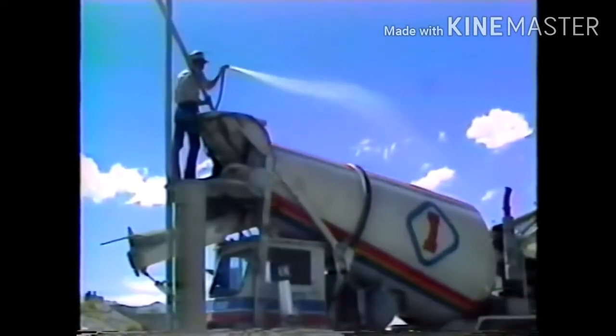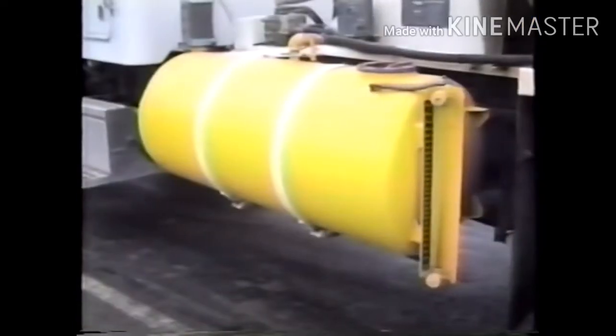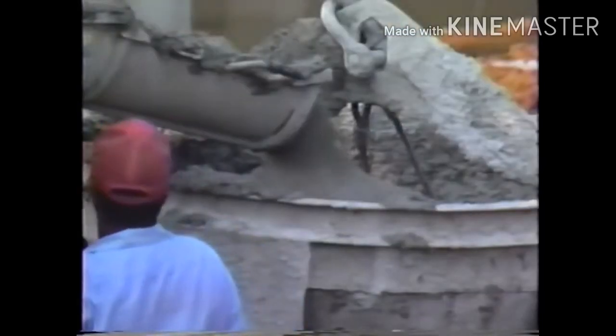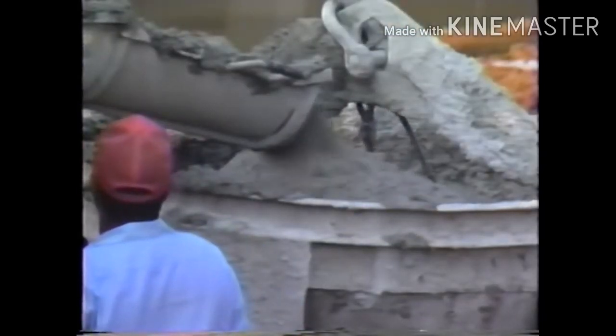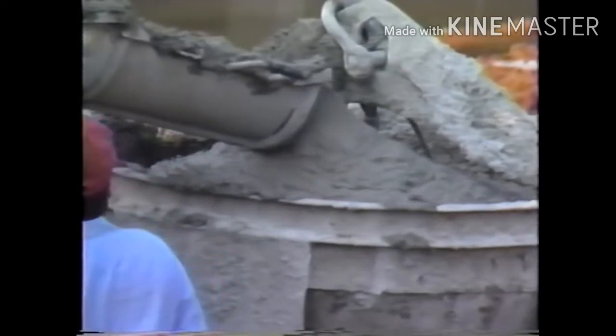For example, if wash water was left in the truck before it was loaded, the mix may be too wet. Or the truck driver may decide to add water if the mix begins to stiffen. So it's important, and it's required, that the quality of the concrete be verified before the concrete is cast.